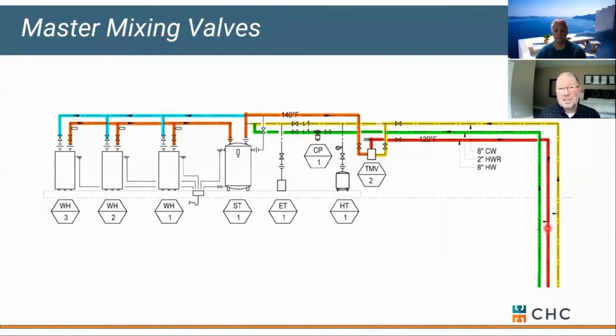Now, when somebody starts taking a shower, we start bleeding water off of this line. Meanwhile, cold water is coming in and giving us accurate flow across a master mixing valve so that we can temper it and send that warm water back down this line. That apparently takes 10 minutes. So the fix to this is to deal with the tie-in for our circ pump, correct it.